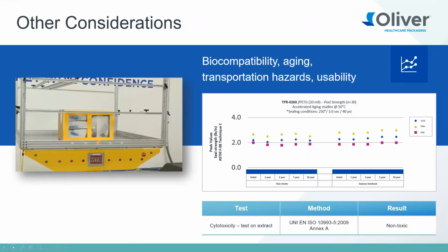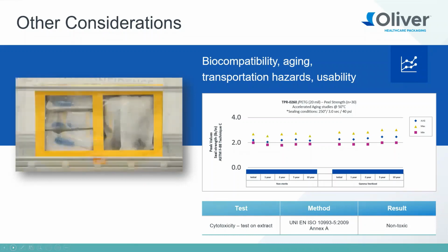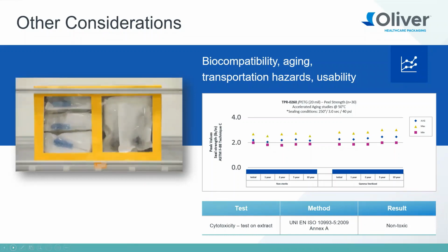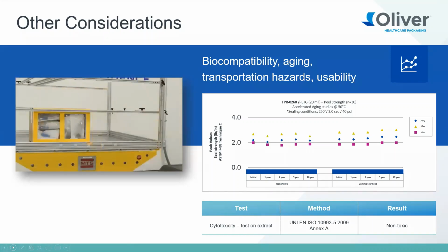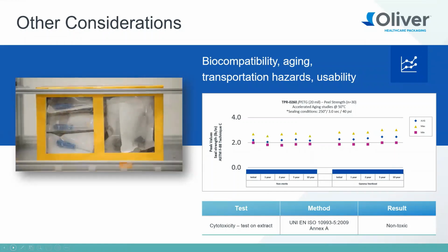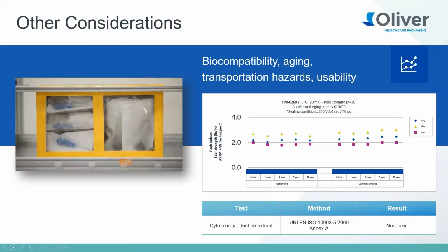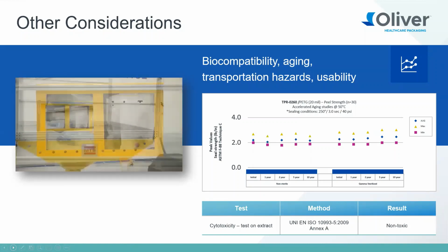So too much headspace can allow for too much movement, and all the thousands of iterations, as we're seeing in this video, could lead to punctures and abrasion problems and so forth, flex cracking within your package. So all things to be mindful of. Again, not all coatings are going to perform exactly the same in a shock or vibration study. So those are just some of the other things too, Sarah, but that's more or less some additional things to consider when you're choosing materials and designs.